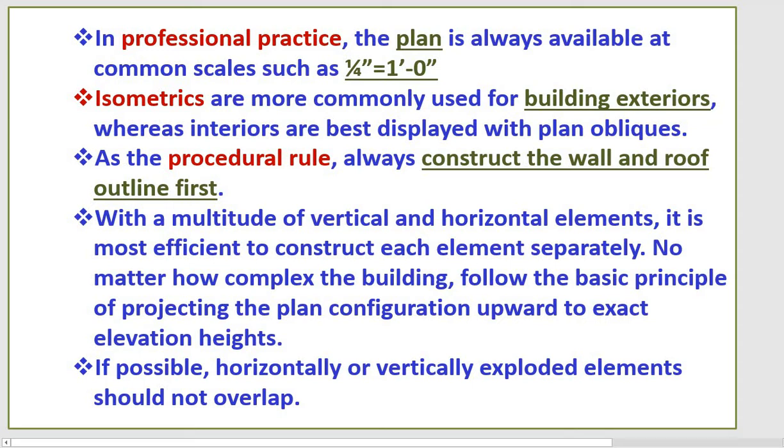You need to know something more. In professional practice, the plan is always drawn at a common scale. For example, they say that 1/4 inch equals 1 foot 0 inches. That means the scale you usually see on the drawing. They use that scale to draw the floor plan.